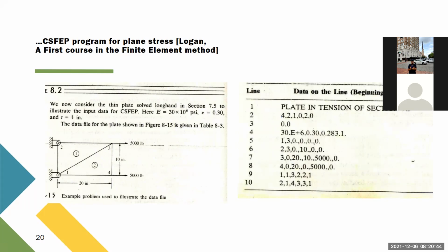So I have 4 joints, 2 elements. This is the one material. This is plane stress, and I have no weight. I have not printed, so neither the element stiffness or the global stiffness, nothing is printed. This is the Young modulus, Poisson ratio, density, and I don't know what else is.